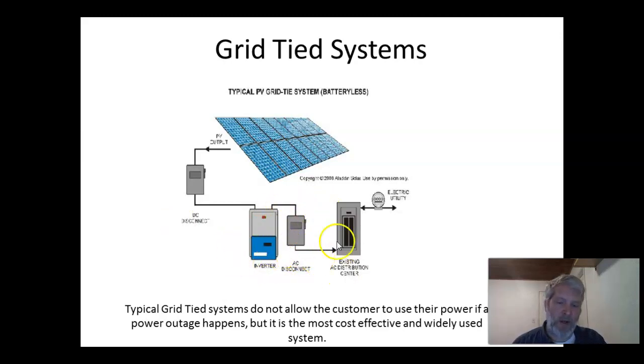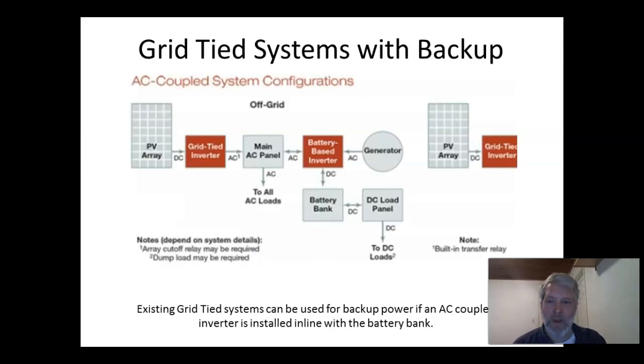Now sometimes the jurisdiction may or may not have an AC disconnect system, because it just depends on jurisdiction. Sometimes they want an AC disconnect so that the utility workers can come out and disconnect your system if there's an issue where it goes down on the grid, and other people say we can do that remotely, and we're going to turn that off anyways through our junction boxes, so we don't really care. So you can just use the breaker.